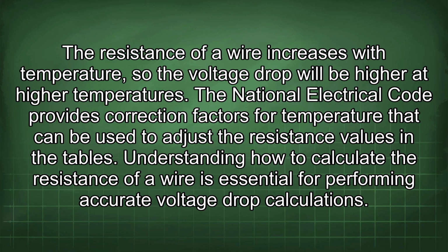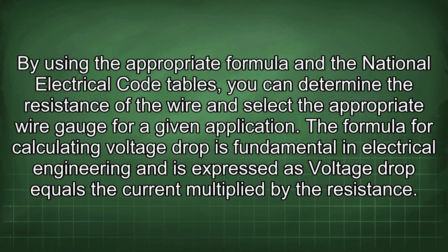Understanding how to calculate the resistance of a wire is essential for performing accurate voltage drop calculations. By using the appropriate formula and the National Electrical Code tables, you can determine the resistance of the wire and select the appropriate wire gauge for a given application.